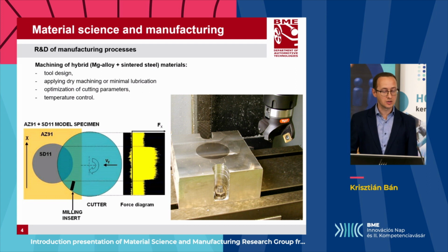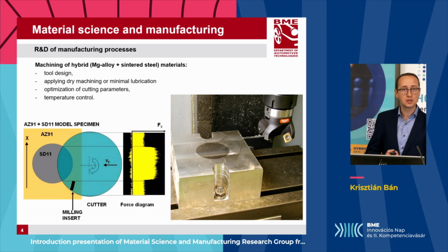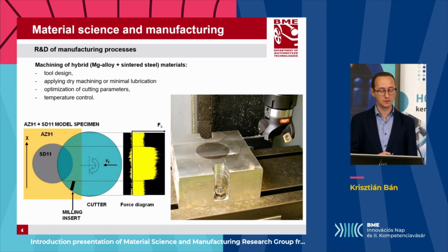Another additional problem was that this manufacturing process had to be performed applying dry machining or a minimal lubrication. Because of the fire hazard of the magnesium, it was another problem. Therefore, we have to perform very serious temperature control in this process.